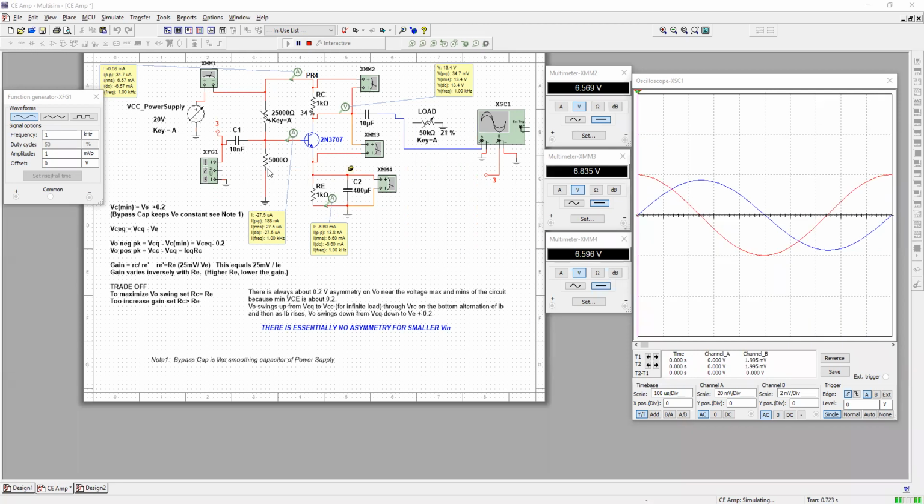So creating a greater separation between the capacitor's impedance and the resistor's impedance will do two things. It will definitely pass more voltage to the resistor, which is the input to the transistor amplifier, and it will reduce the phase shift.